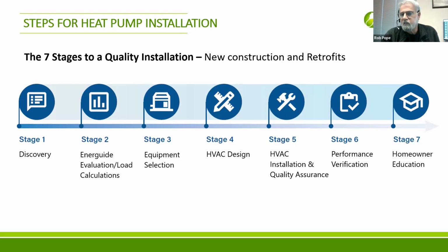We like to put MERV 11 or better in the houses. So you need the ability for that air to overcome the pressure drop from a good filter to provide indoor air quality in the building. And then it's moving ducting around. That's usually the issue. Ducting, in a lot of cases, if it's not well coordinated, creates drops and furred walls and that kind of stuff.